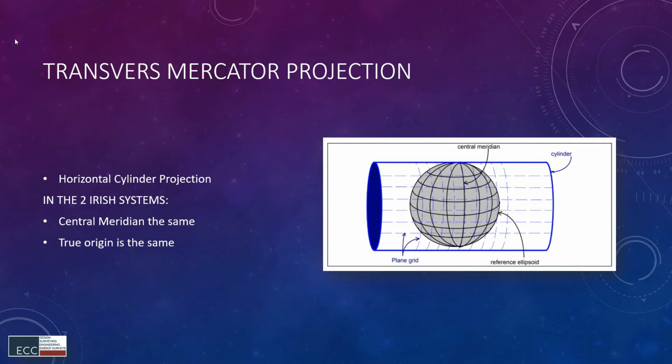So this is how it looks. After you set the projection, you have in the job your global WGS84 lat long coordinates, and you also have your grid. The grid coordinate is the plane, and there is a mathematical projection. Almost every geodetic projection keeps the angles right.